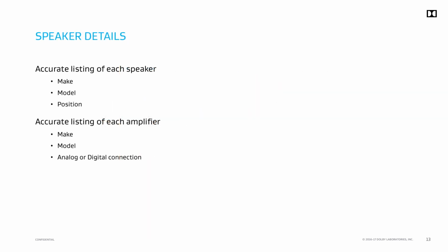In array assignments, the speakers will be automatically grouped according to default arrays, but can be regrouped if any changes are necessary. Under speaker assignments, select the loudspeaker type, make and model, as well as the amplifier make and model for each speaker within the room. Area selection of speaker groups can simplify defining multiple speakers that are the same make and model. Map output routing to the corresponding speakers with the Routing tab. Next, associate the Bass Management subwoofers with the nearby surround speakers using the Bass Management tab. Once all room information has been accurately entered into DAD and confirmed on site, then it is time to check if calibration can be started.